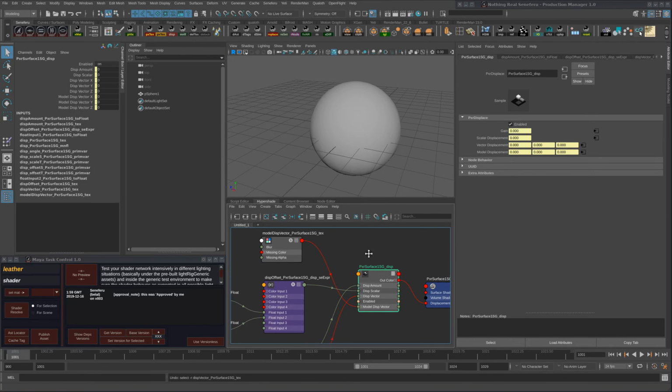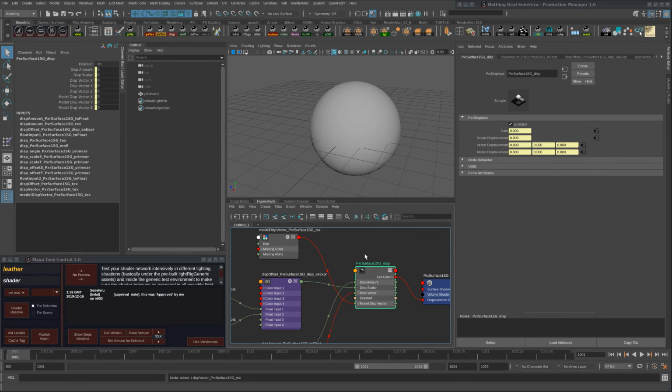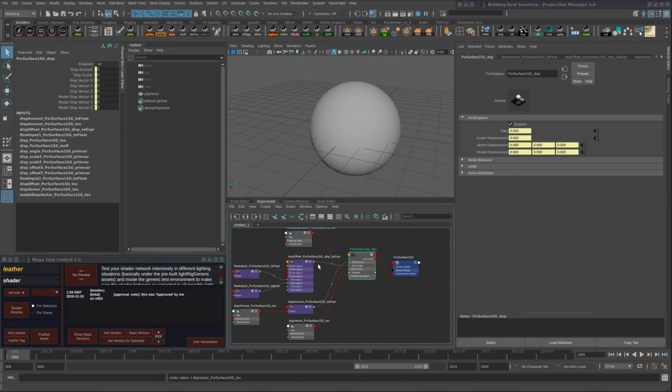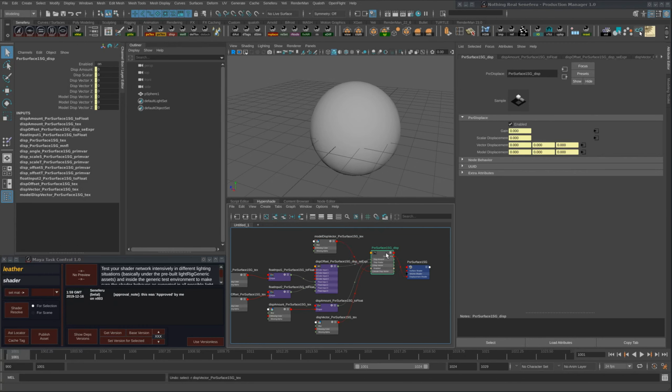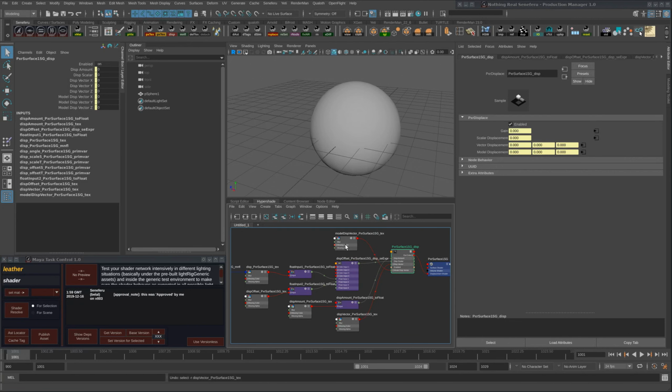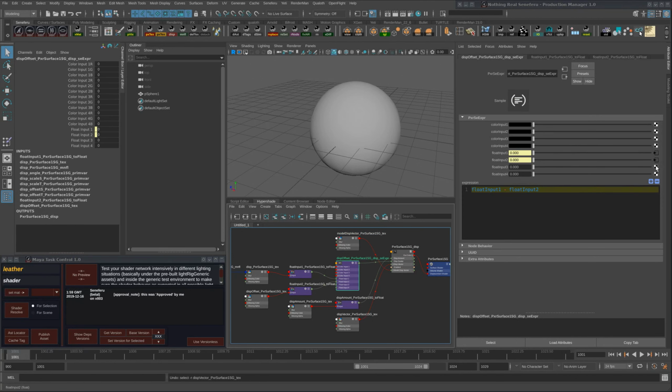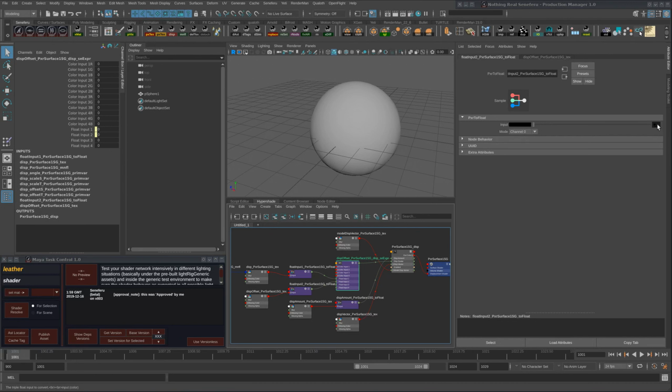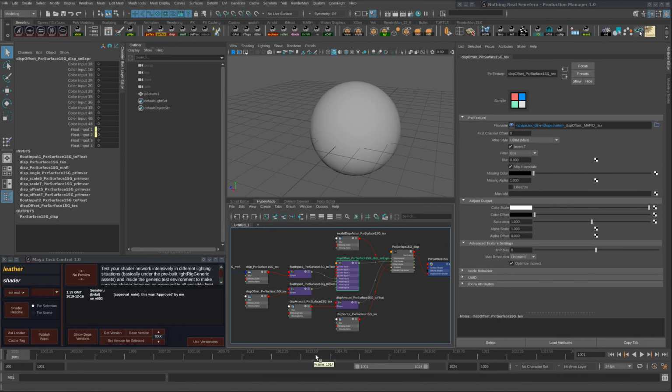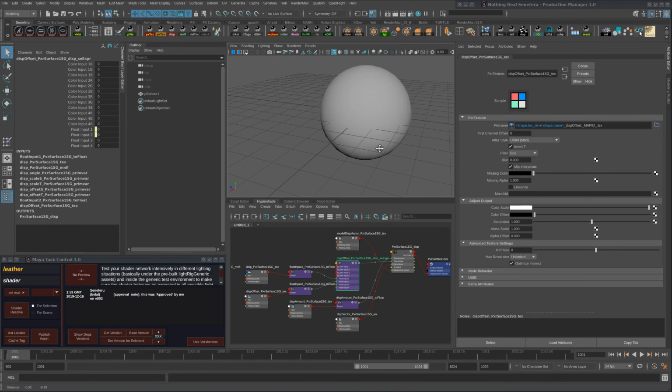But if you know that you are using world space displacement, or you are not using centered maps, then you can assign a black texture to this offset, so it becomes 0, then the offset will have no effect.